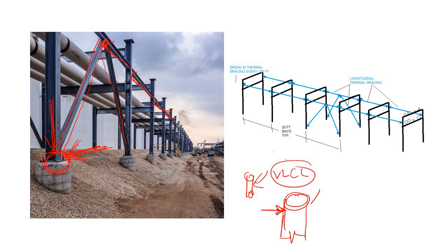And if it is not sufficient, let's say you have a large lateral load, in that case this horizontal component also becomes very high. In that case you may have to provide two or more piles to satisfy this horizontal force carrying criteria. Okay, so that's it.